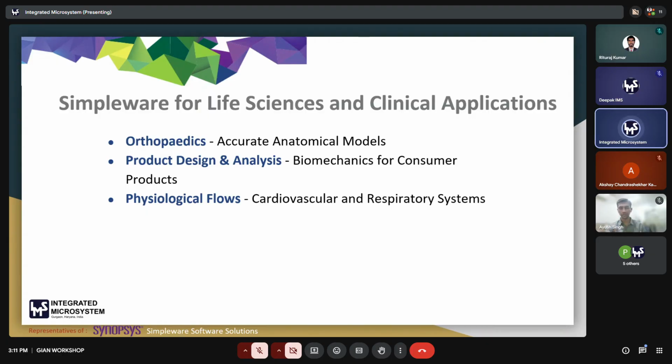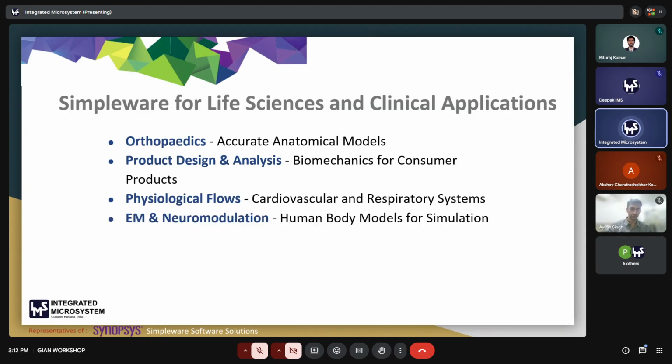Whenever we are doing the 3D image processing, we can basically develop different planes, and we can set them along any n number of surfaces that we are having. So we can have the MPR visualization, and ultimately we can set out the inlet points, outlet points. We can set out the contact points, node sets, and a mesh can be defined then for any specific region. And any sort of CFD simulations, FE simulations can furthermore be conducted.